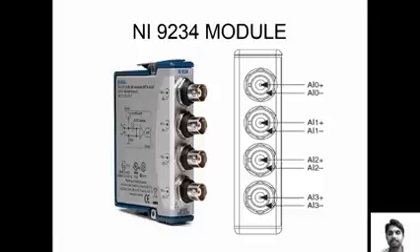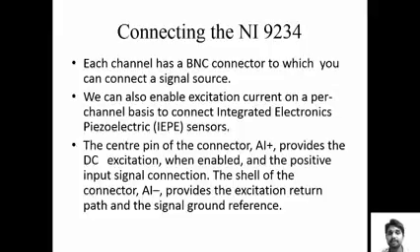Next, connecting to the NI9234. Each channel is connected by a BNC connector. This is a connector by which you can connect the signal source. You can also enable excitation current on a per channel basis to connect integrated electronic piezoelectric sensors.